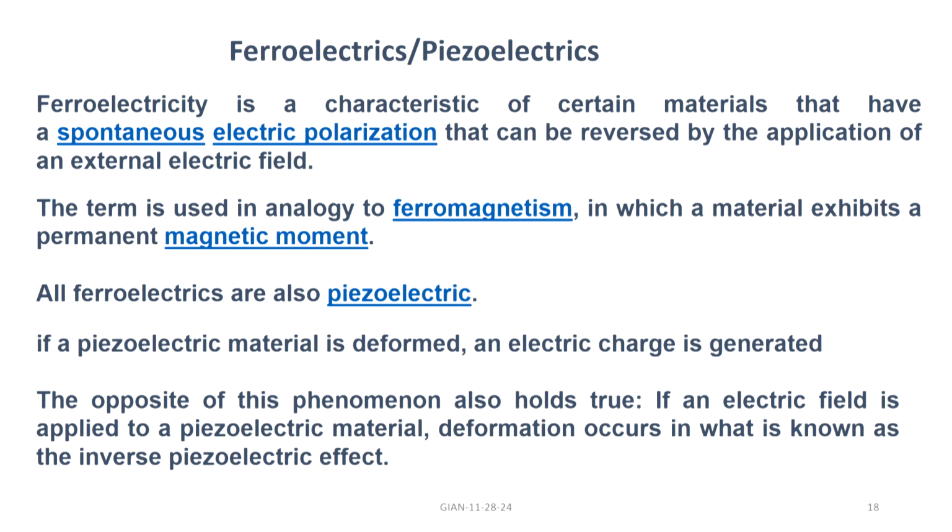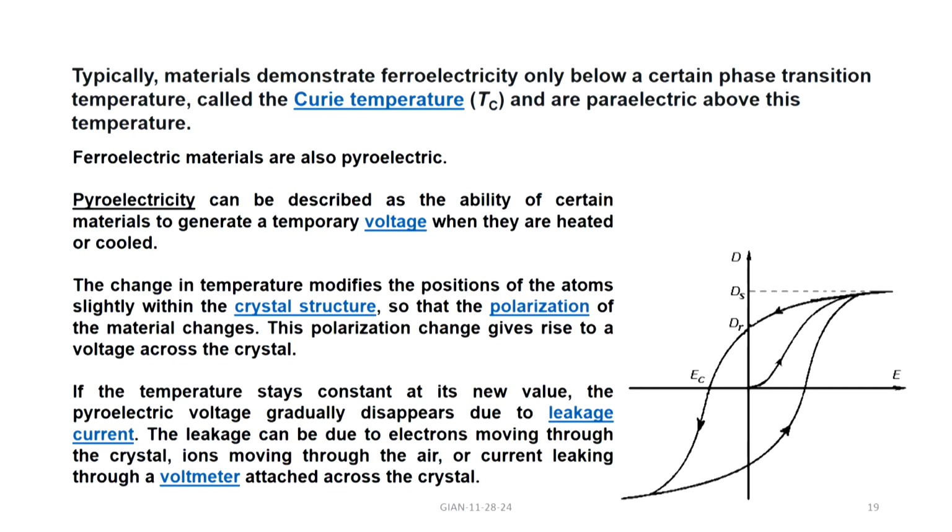And piezoelectrics, they are not ferroelectrics. Most all materials are piezoelectric in the sense that if you apply an external electric field, there will be mechanical deformation, such as quartz or aluminum nitride. These are not ferroelectrics, but they are all piezoelectrics, because there is always a change in the charge configuration that will lead to a dipole moment under only external electric field.